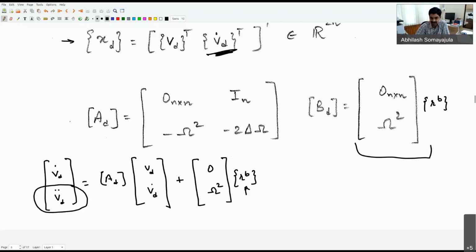Otherwise, if this integration functionality was not there, if this second order system was not there, and I was directly just giving it, then the step input would reflect as a step input in the VD. If I did not have a low pass filter but a direct filter, where whatever comes in I just pass on, then whatever input I give, a step input, would be directly passed on.